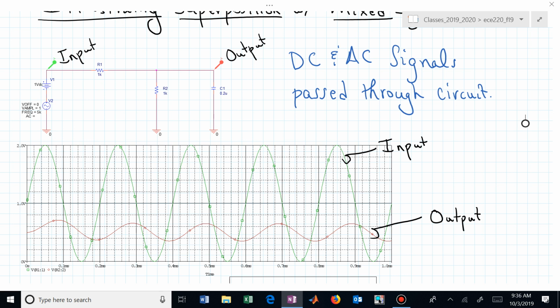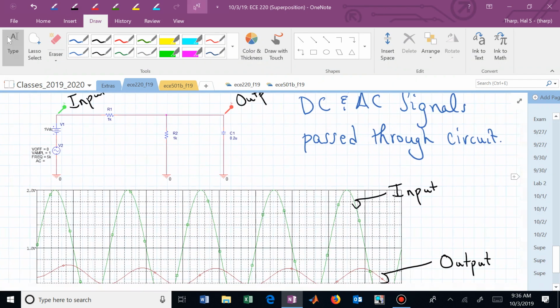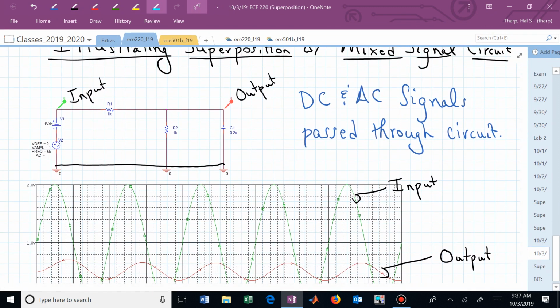This is drawn maybe a little differently. Maybe you're used to seeing the bottom connected, but it's connected through the same common node. These are all the same. Those are at the same potential. They're at ground. They're our reference voltage. So we do have currents flowing through the circuit, and we have voltages across these devices. But if I simply got rid of that, do you see you just have a voltage divider?